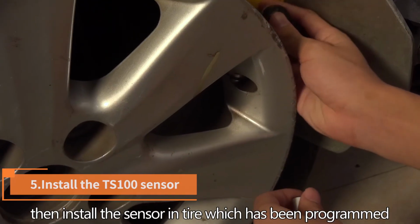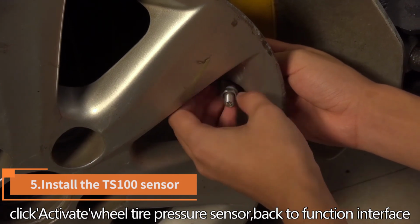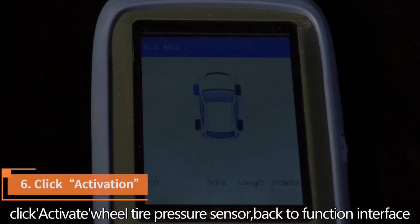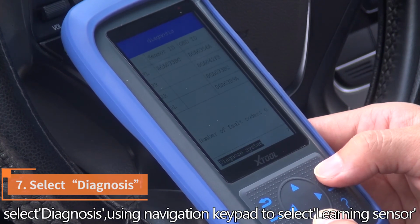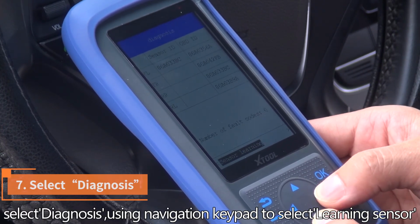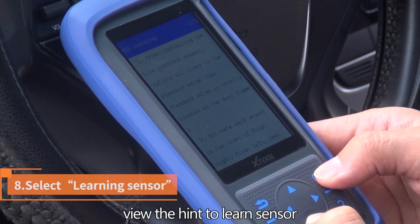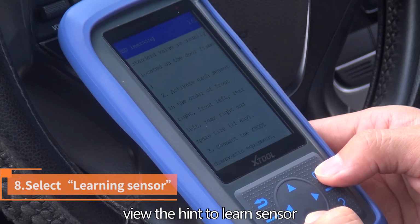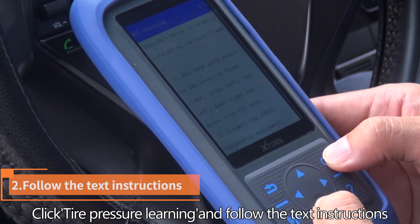Then install the sensor into the tire which has been programmed. Click Activate Wheel Tire Pressure Sensor, back to the function interface. Select Diagnosis. Using the navigation keypad, select Learning Sensor. View the hint to learn the sensor. Click Tire Pressure Learning and follow the text instructions.